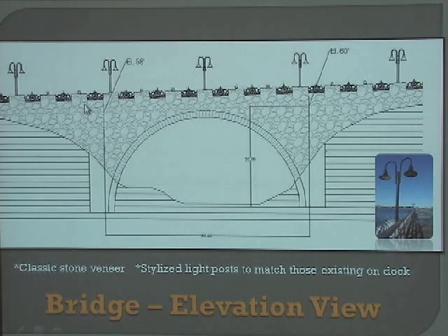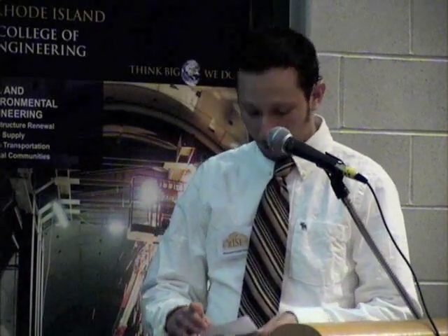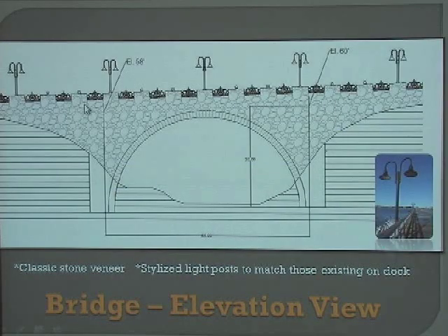Our bridge is designed to be consistent with the geometric requirements of the railroad, such as the Federal Highway limits, requirements for DOT, specifications of the American Railway Engineering and Maintenance of Way Association, and the criteria established by Amtrak. The code we used for this design was HL93, as described in the AASHTO LRFD specification. The bridge roadway and sidewalks were designed to the AASHTO policy on geometric design of highways and streets.